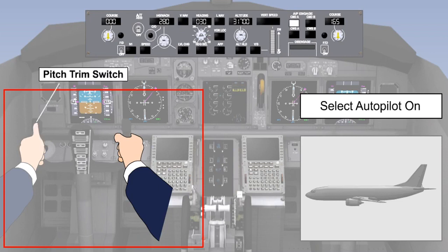When the pilot is flying the aircraft with the autopilot disengaged, he will trim the aircraft manually. Fly-by-wire aircraft have a full-time auto-trim system that operates in autopilot and manual control. Most airliners have a trimmable horizontal stabilizer and elevator combination for pitch trim and control.